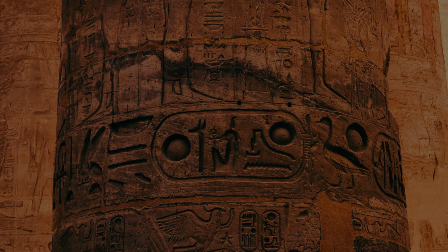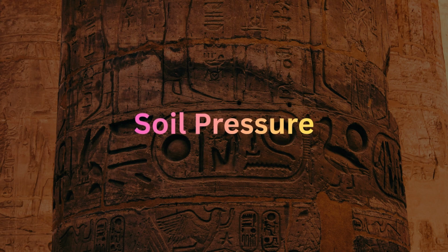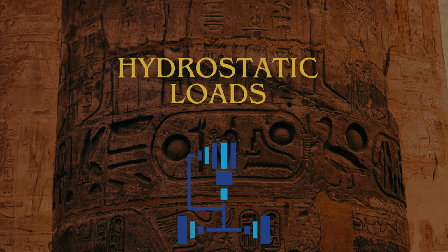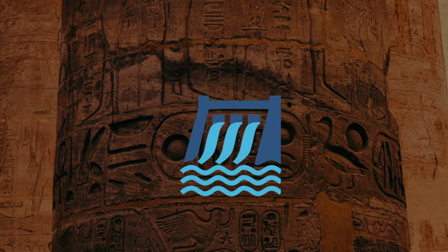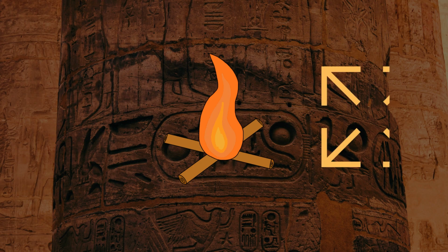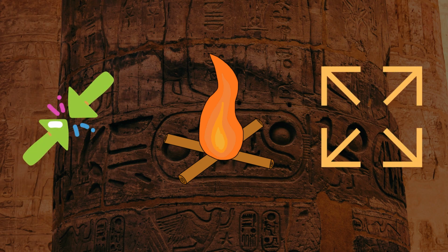But wait, there's more. Engineers also have to calculate soil pressure, the lateral force of dirt pushing against retaining walls or basements. And if water is involved, we deal with hydrostatic loads, the pressure of still water, like against a dam, and hydrodynamic loads, the crushing force of moving water. There are even thermal loads, where structures actually expand and shrink as the temperature changes.